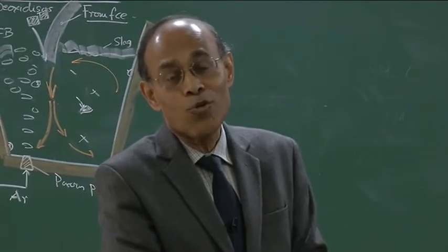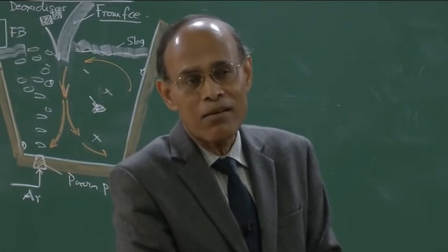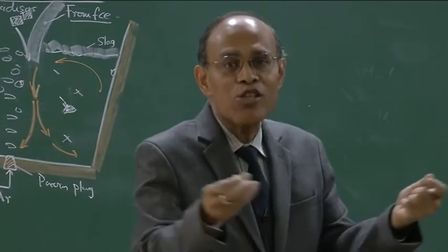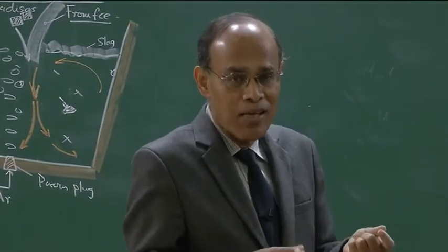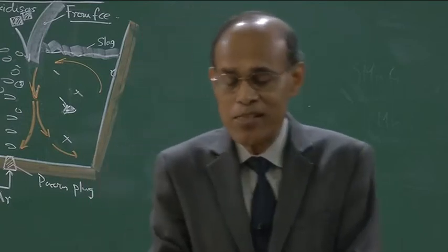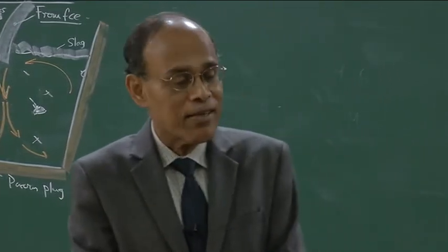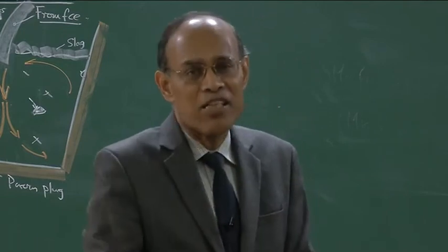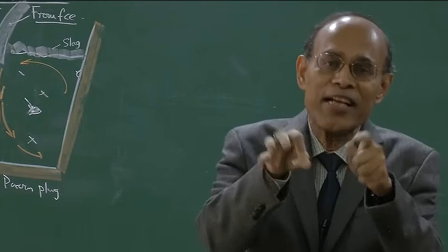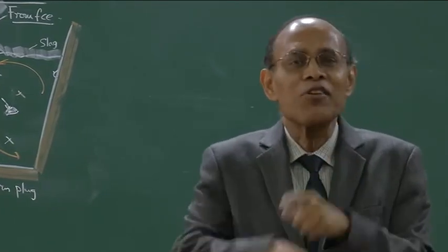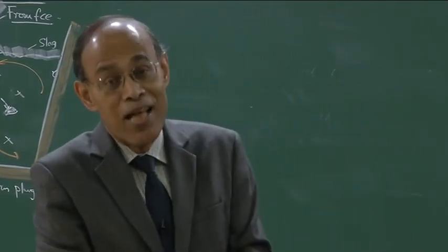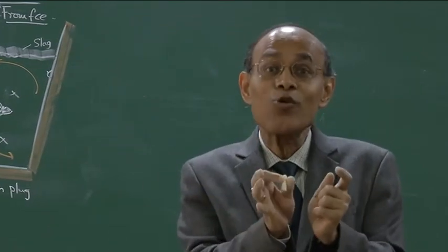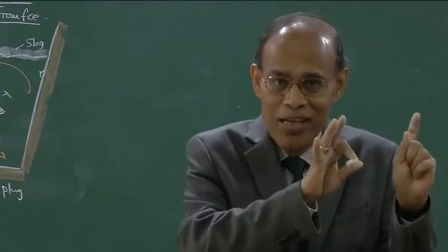So we could expect that the deoxidation reaction will proceed towards equilibrium quite fast, and there will not be much barrier to nucleation. There are so many kinds of solids, walls, vessel walls, and nucleation, as you know, is mostly heterogeneous nucleation. So therefore we can expect that the deoxidation reactions will go to completion within a very short time following the addition. So the equilibrium between melt and the deoxidation product is going to be established. Whether the deoxidation product and the melt are simultaneously going to be in equilibrium with the slag or not, that is a different issue that we do not ask.